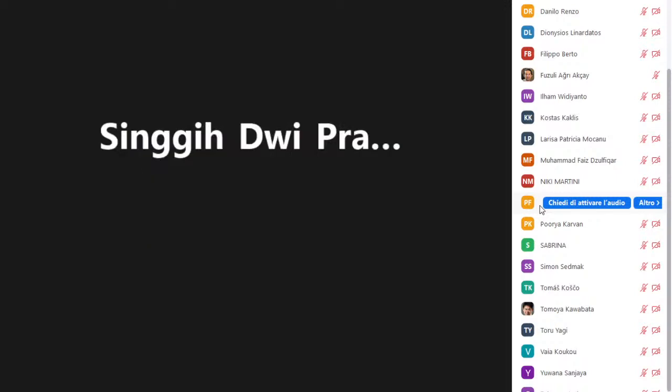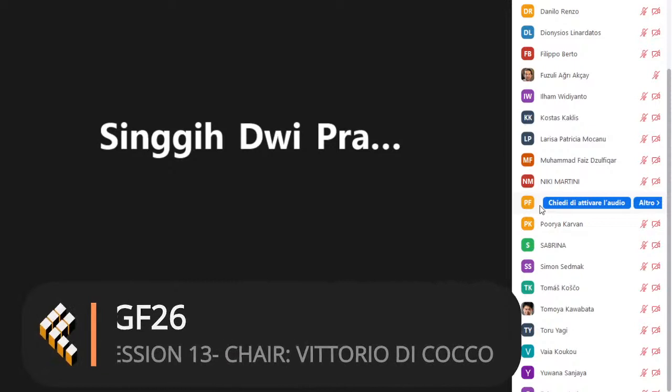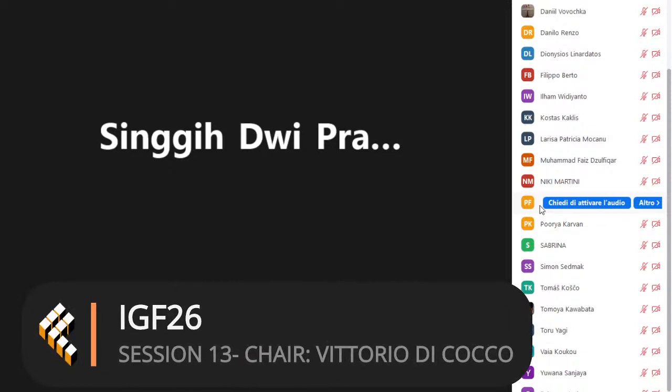Okay, thank you. In my work, the procedures for fitting and welding are performed at the time of fitting. Welders must also consider the shrinkage due to welding. Tack welds must be conducted by qualified fitters, and welding is carried out following the welding procedure. Welding is performed using a gas tungsten arc welding machine, GTAW, AWS class ER70S-6.